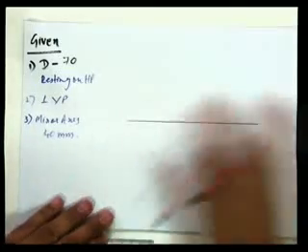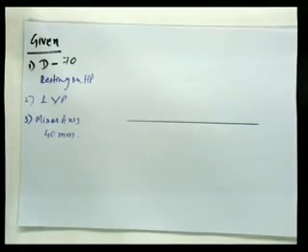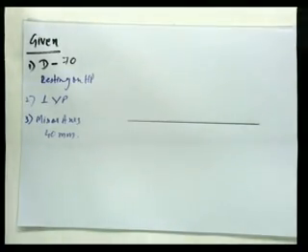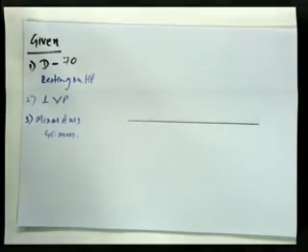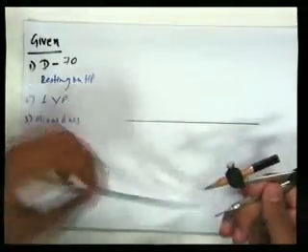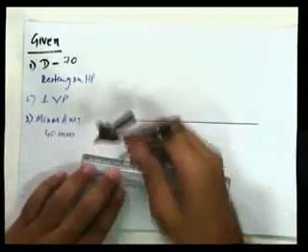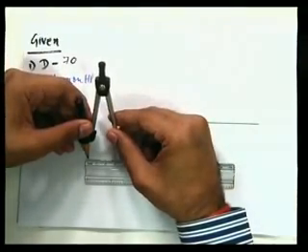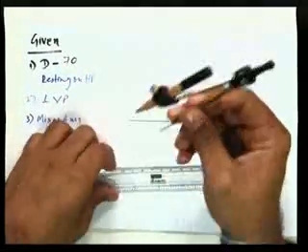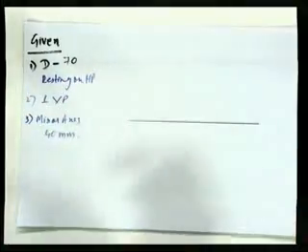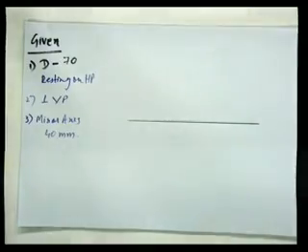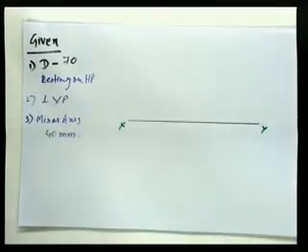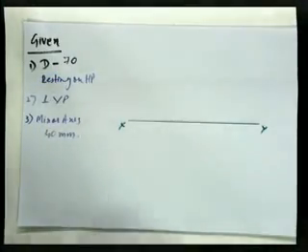Now first of all we'll take diameter as 70 mm, so the radius would be 35 mm. And as it is resting on HP, the top view would be a circle, and the front view would be a straight line, and the top view is below line XY as it is in the first quadrant. There's nothing given, so we'll take the first quadrant.